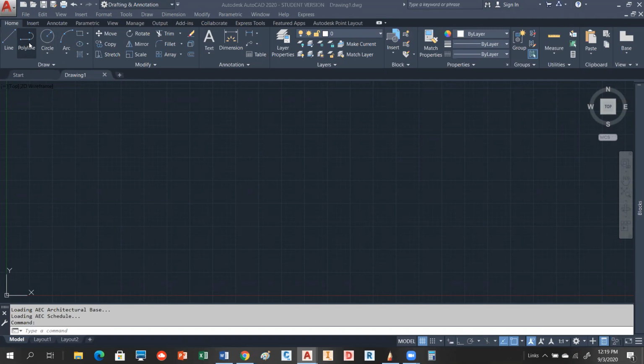Yes. Okay, great. All right, so the P-line command is over in the Home tab of the Draw section. The P-line right next to the line. P-line stands for polyline. And so what it is, it's a command that will allow you to draw lines connected.